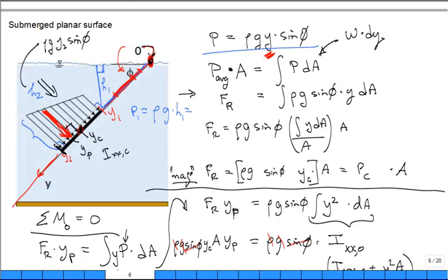In statics, we always take the rectangle and the triangle by itself. Okay, I'll show you that. But this equation is full of mathematics. This resultant force right here, F of R, is equal to the pressure at the centroid times the area. That works for a triangle, a rectangle, or this load, which is a combination of both. It gives you the right magnitude.